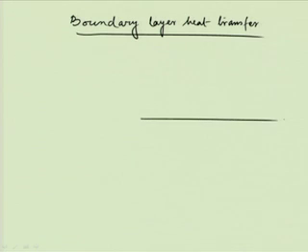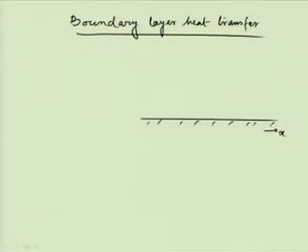So, if I say it is like this, for a flat plate of this kind, so this is the flat plate of some width in this direction, and a flow is there in this direction. Say that direction is the x direction, along x there is a flow. Before it enters, this point is called the leading edge. I will say point O is the leading edge.